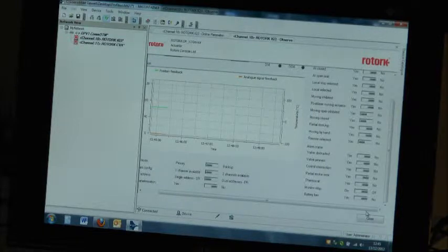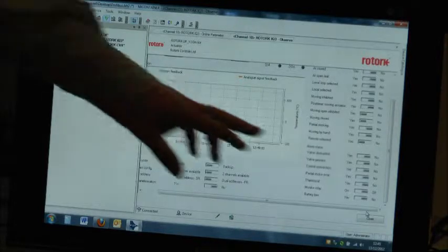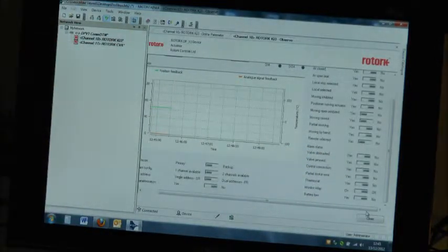But if it's at the top of a flare stack and it's very cold outside today, you possibly don't want to go around your plant checking all of these things. So it's a nice way of checking for status bits here. Also, in some PLC systems, I found the vendor licenses the number of tags or something. So you don't always get that much information available back.